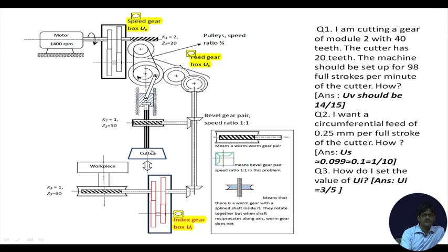The cutter is represented by a trapezium. But up till now, you have noticed that we have referred to the cutter as just another gear, a perfectly made gear. Then why does it have this trapezoidal shape? At least if it had been circular in shape, that is, if it had been represented by a perfect cylinder, it should have come out as a rectangle, just like the workpiece with an axis line.